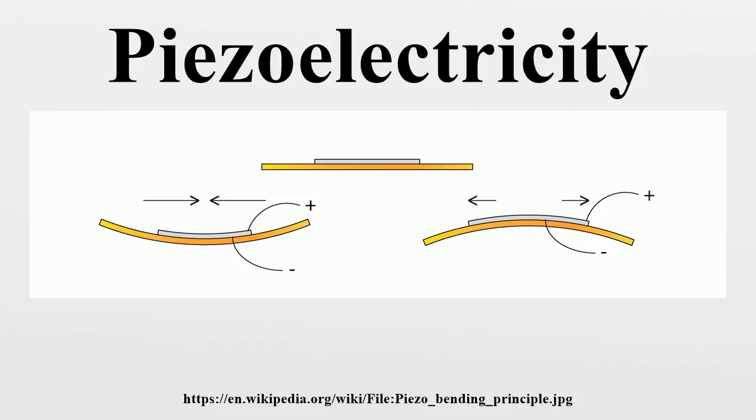The superscript E indicates a zero, or constant, electric field. The superscript T indicates a zero, or constant, stress field, and the superscript t stands for transposition of a matrix. Notice that the third-order tensor d maps vectors into symmetric matrices. There are no non-trivial rotation invariant tensors that have this property. That is why there are no isotropic piezoelectric materials.